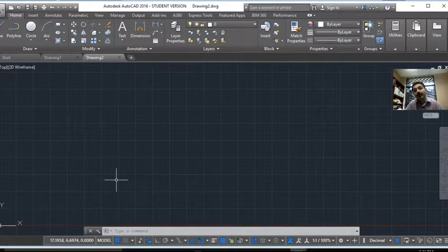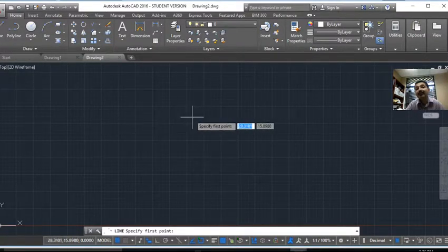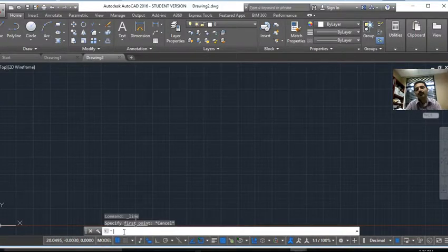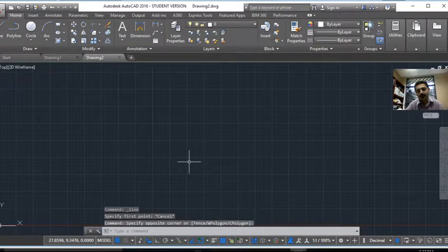drawing things using AutoCAD. You can do it by a simple click, like if you go all the way to the Home tab and click the very first icon here, line. This is how you can activate or ask AutoCAD to start drawing a line. Or you can draw things and do most of the things using the command line. You can get to know how the command lines go.